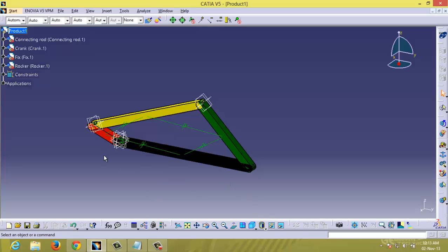Now all the 4 links are constrained, that means assembled, and they are also joined with joints. That's all, the joints here are revolute joints. For different modes of kinematics, you can create several types of joints, and a collection of joints can be seen here.